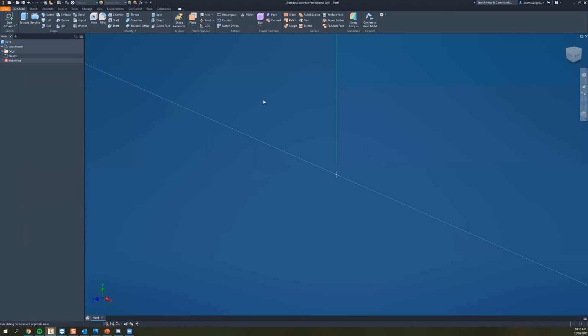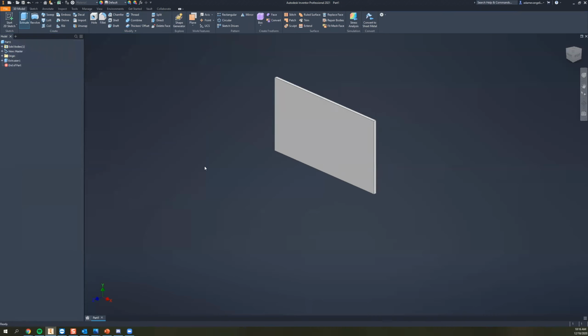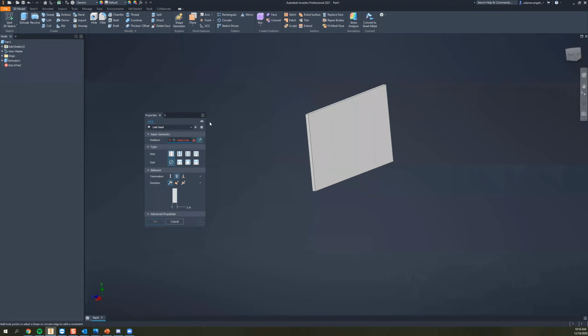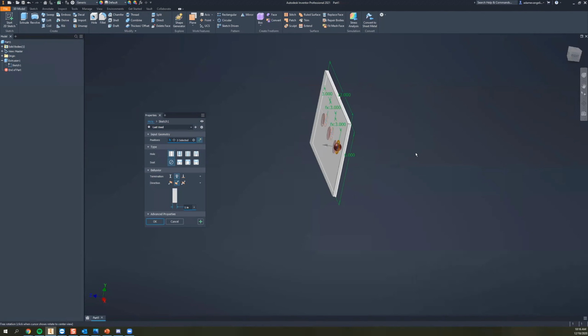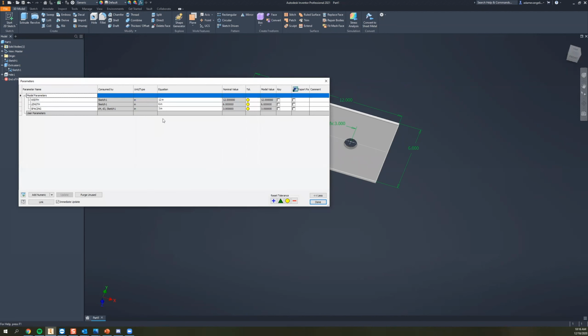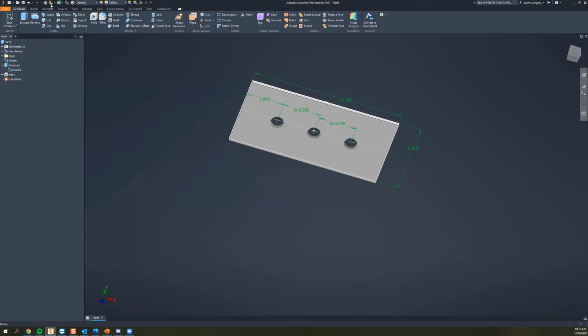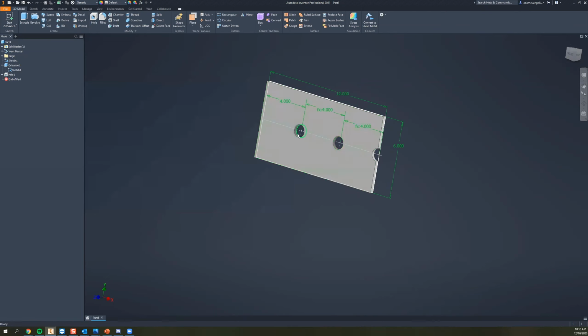So I'm going to finish this sketch, for example, and we'll extrude it like 0.25 inches, sure. And we'll do the whole command over here after we share the sketch, just so that we have a proper reference or something like that, right? So I'll go ahead and click OK. And again, if I wanted to, I could come back over here and we could make spacing something a bit more interesting, maybe like 4. And we would expect the spacing to update after we hit the update button, make it 4 inches instead, right? Could I have chosen a better orientation for these holes? Absolutely, but I think the concept stands here.